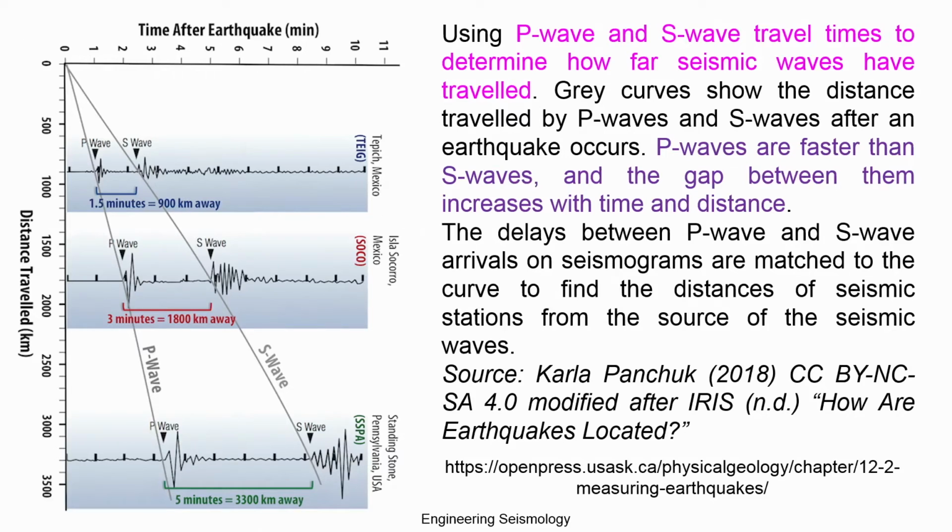We also discussed that picking the arrival times of the P and S waves helps you identify the epicentral location of the earthquake if you have three stations. If you have three or more stations, you can also get the hypocentral or focus point, the depth of the earthquake. Today we will start again with the epicenter. For a given earthquake recorded at at least three places, we need to precisely identify the earthquake. We are going to see how the P and S waves change with distance at these three stations.